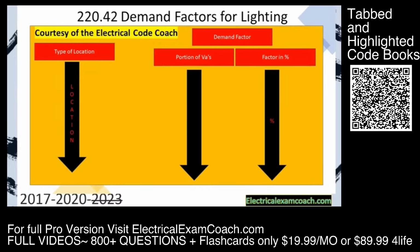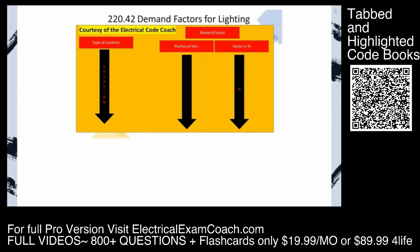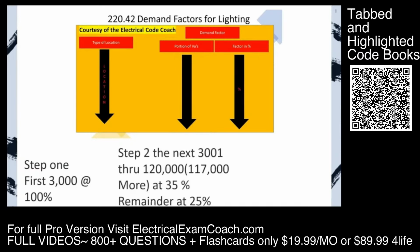Let's get to it. When looking at this table, we're going to see a multi-layered demand factor for dwelling units. Step 1, we're going to take the first 3,000 VAs at 100%. Step 2, we're going to take in between 3,001 through 120,000, which is technically just another 117,000 more for the rest of the program. We're going to take that percentage at 35%, and above and beyond that at 25%. Then step 3, we add them back together.